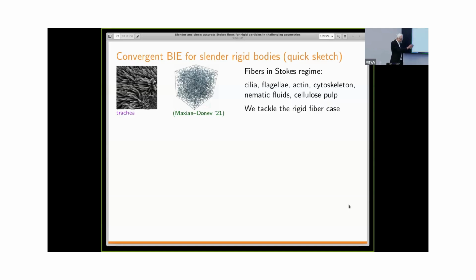There's a lot of problems with discretizing high aspect ratio bodies. The usual one being that the way surfaces are discretized generally involves order 1 aspect ratio objects. So when this is epsilon and this is 1, then you immediately need 1 over epsilon degrees of freedom, and you're kind of dead if epsilon is 10 to the minus 4 or something.